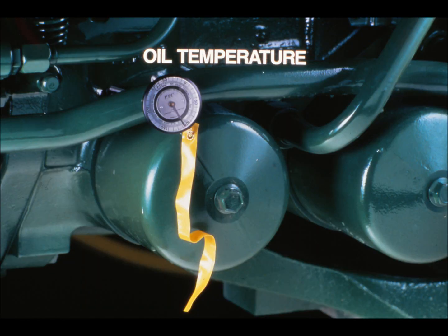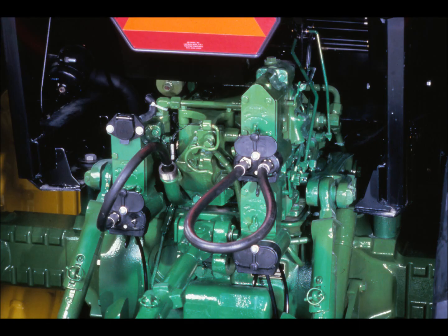Install a 100 to 240 degree Fahrenheit temperature gauge on the transmission oil filter to measure oil temperature. Step number 6 also gives you the procedure for warming the oil to 110 degrees. Perform this procedure before doing any tests. The procedure involves putting a jumper hose across one SCV and dumping oil to sump from another SCV. You can also put a piece of cardboard over the oil cooler to heat the oil faster. With all gauges installed, you are ready to proceed with the diagnostic procedure.